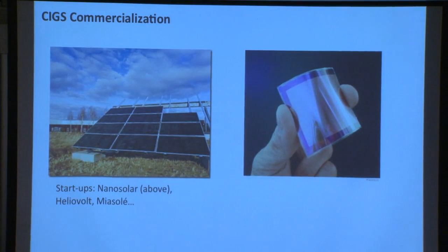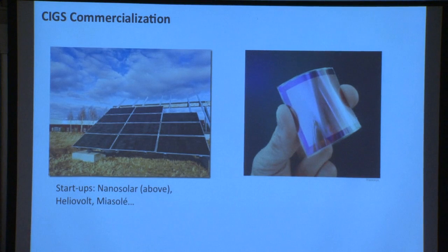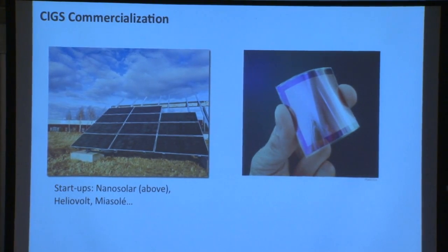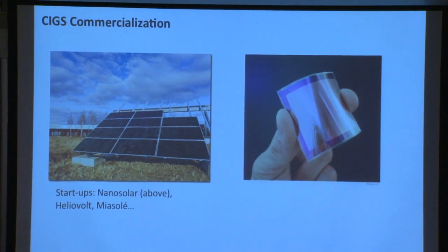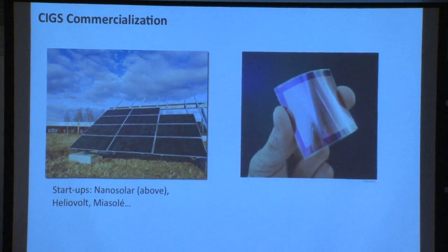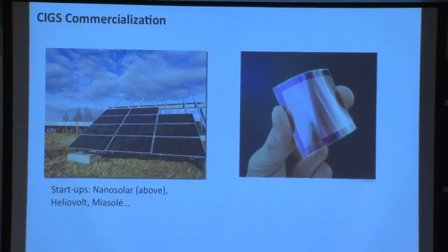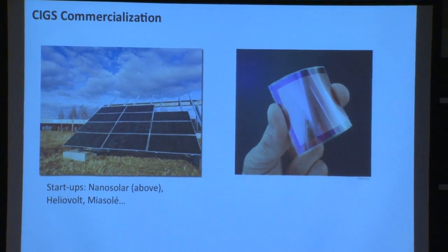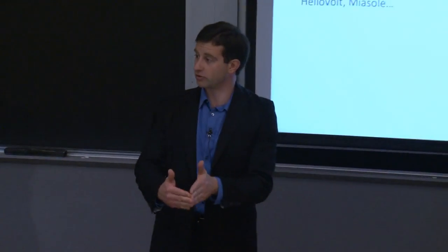And so the ultimate form factor for the devices was to chop them up into areas not too dissimilar from an actual crystalline silicon device. So they chopped up their layers into individual discrete cells, and then connected and soldered them together, much like a crystalline silicon device would be put together inside of a module. So the dream of an inline thin film process, roll-to-roll, was reaching an abrupt wall in the development process because of the lack of large-scale uniformity.